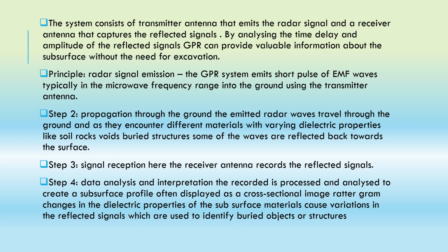By analyzing the time delay in between sending, emitting the radio signal, and receiving the reflected signal, and the amplitude of the reflected signals, GPR can provide valuable information about the subsurface without the need for excavation. So this is how it works. The principle of radar is radar signal emission. The GPR system emits short pulses.